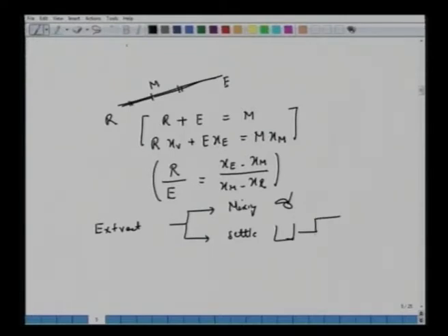And when we settle, there is a phase separation: extract phase and raffinate, which we also sometimes call residue. The extract will contain what we have extracted using a solvent, right? And raffinate is your feed, which will also contain some solvent, but C is smaller here and larger there. Some A will also go there, and some solvent B will also go here. Okay, so this is your introduction to the phase diagram for extractions.